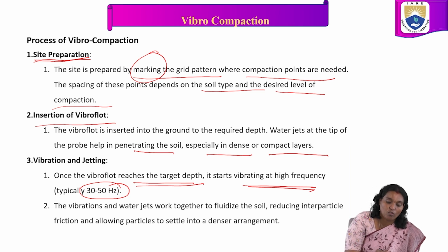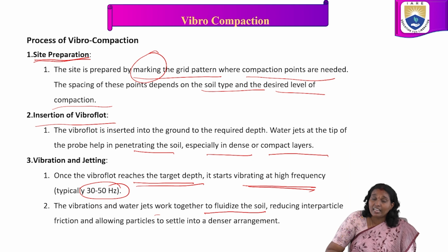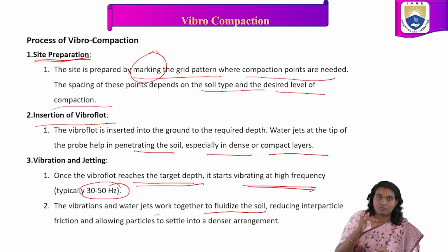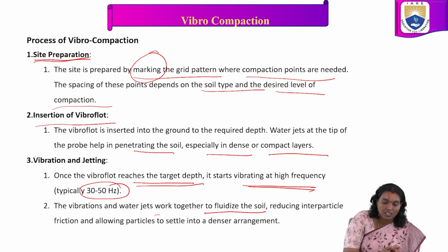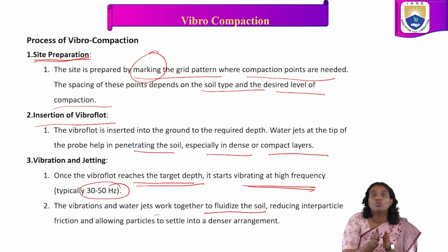The vibrations and water jet work together to fluidize the soil, reducing the interparticle friction and allowing particles to settle into a denser arrangement.